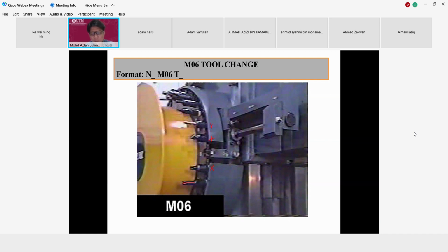Sometimes in newer machines, there is a computer there. You put in tool number 1, then you can save to the monitor what tool you put, because the machine doesn't know the tool. It doesn't have its own brain to recognize the tool. You just put it in and it's stored in what we call the tool magazine without knowing what kind of tool you inserted. So you have to tell the machine how big the tool length is, and what the diameter is.